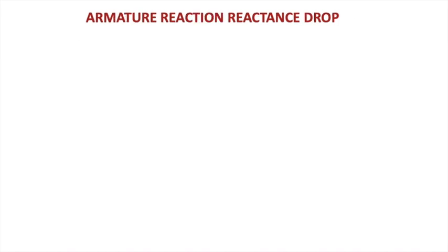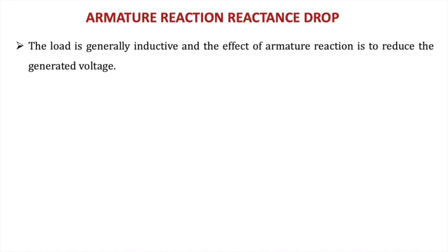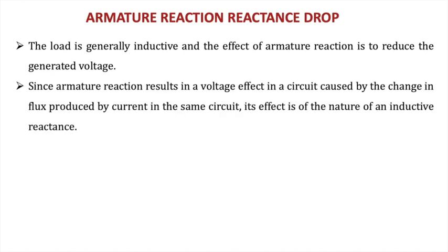Now what is the armature reaction drop? Armature reaction, as I told you, will be similar to the reactance drop. The load is generally inductive, and the effect of armature reaction is also to reduce the generated voltage, because most of the loads you have in your home are not capacitive in nature but inductive in nature. That is the most popular form of load, and we will try to analyze the armature reaction due to that inductive load.